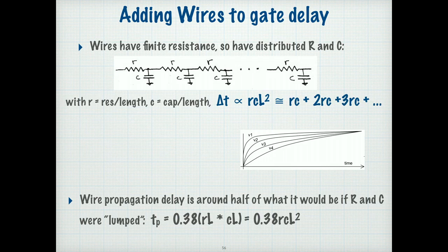And that's because if the wires are long enough that we need to consider their resistance, then we model it this way, as the distributed sections of R and C. As I said the other day, for very short wires, the resistance of the wire is relatively small compared to the resistance of the transistors driving it. So we just ignore that resistance and think of the wire as nothing but a capacitance, which contributes to the load capacitance of the logic gate. But there are cases when we need to consider both. The resistance is always there. It's not that it doesn't factor in, it just factors into a very small percentage. So our approximate models can ignore it.